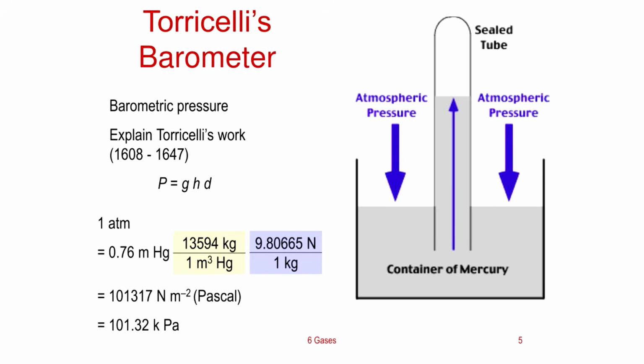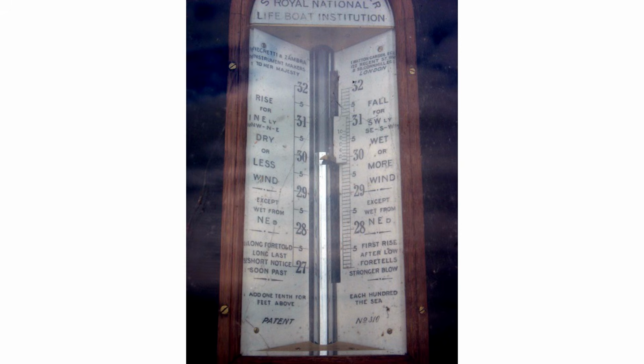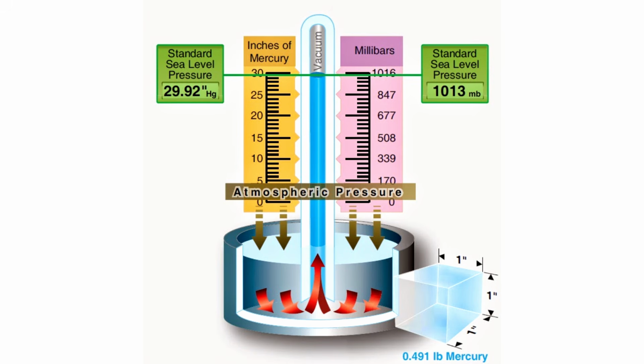with 0.000001 atmospheres of pressure. And that's why you have these mercury barometers, where you would have a U-shaped tube with a vacuum on top of it, and depending upon the height difference between the mercury, you could tell the atmospheric pressure. When I go flying, the pressures get read out to me in inches of mercury, right? 29.92 inches of mercury is a standard atmosphere, and that's the sort of central point of the altimeters.